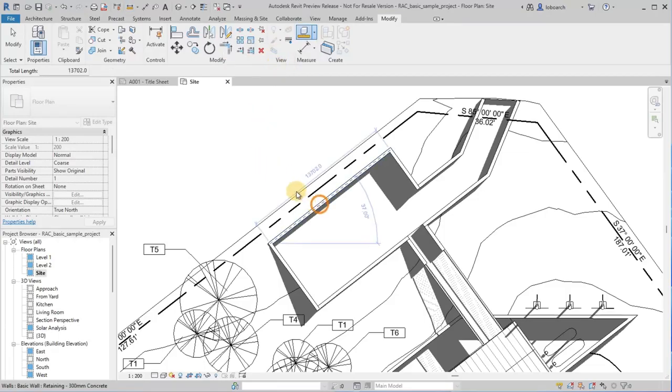Click Measure along an element and then click a linear element in your model, such as a wall. The length and angle of the element is displayed. You can also press Tab to select a chain of linear elements. In this case, the length and angle of each element is displayed. The total length of all elements is shown on the options bar.